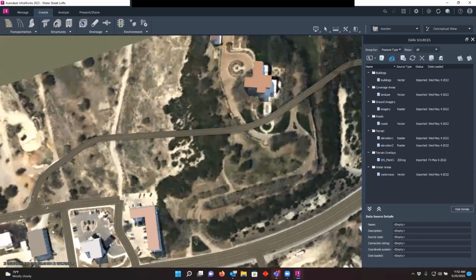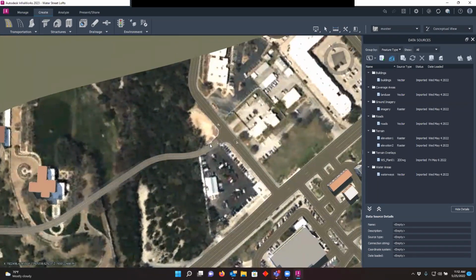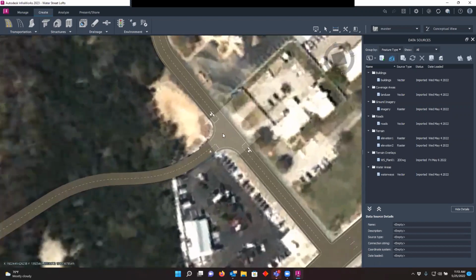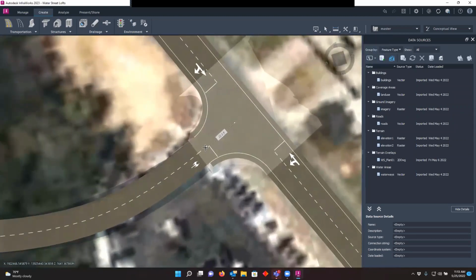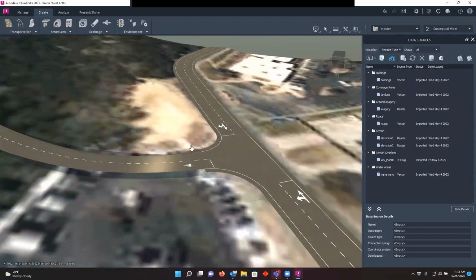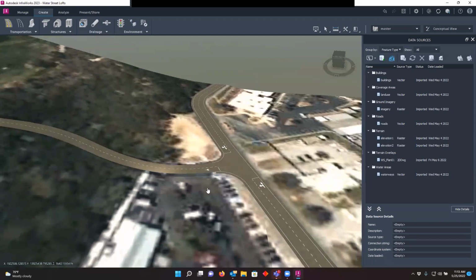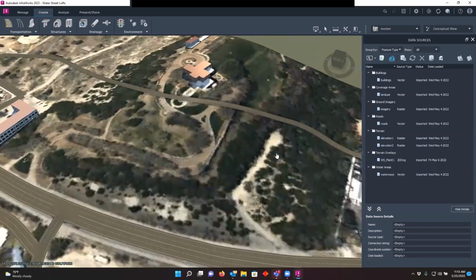So when you're doing this, and we're not doing this today, but when you're bringing it back into InfoWorks, you want to make sure that you get a distance from the center of the road to the ER, right? So you want to come back all the way to the ER, and it's roughly 34 feet. Okay, we'll call it 34 feet. The reason you do that is because when you bring the model back into InfoWorks, it won't show that car going all the way into the middle of the intersection, right? It'll just kind of disappear here before it gets to the intersection. And that's what you want for visual purposes, okay? So keep that in mind.